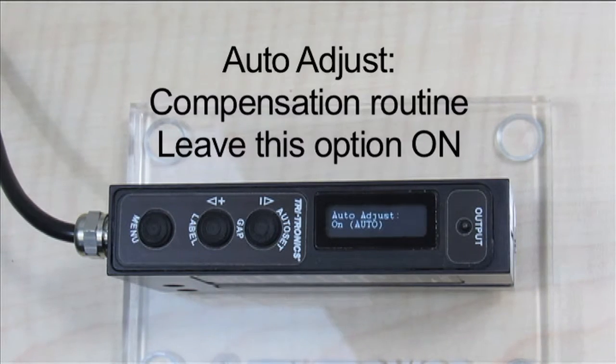The Auto Adjust option engages a compensation routine that automatically adjusts for small changes in signal levels between the gap and the label over time. This option is on by default and should be left on unless instructed by Tri-Tronics Tech Support to turn it off in your application.